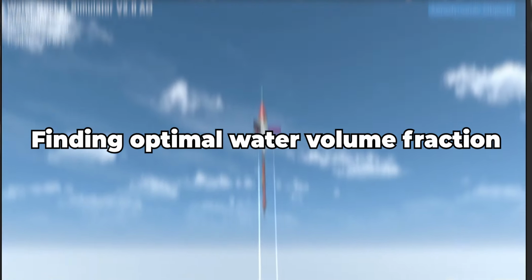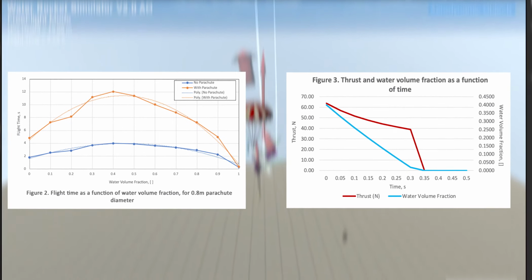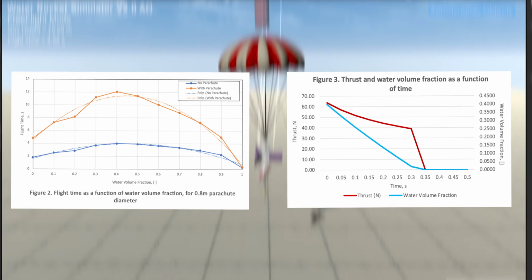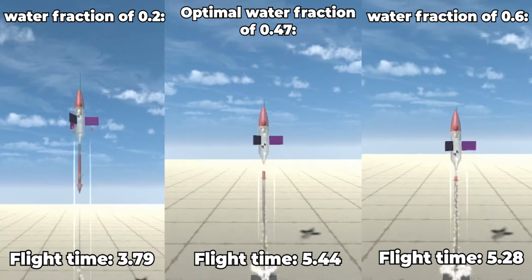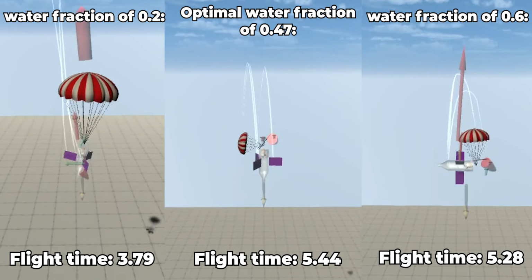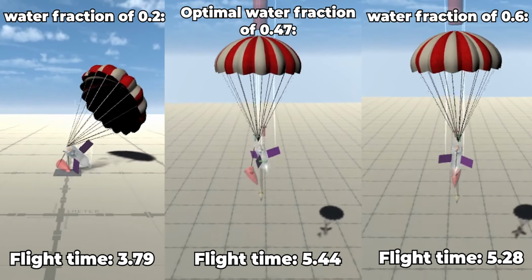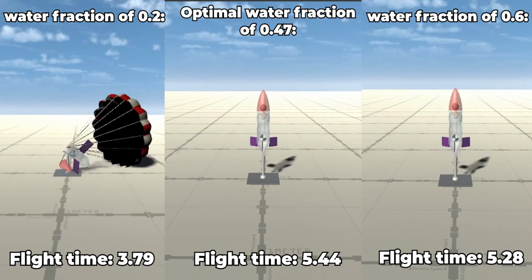Let's see how to find the optimal water volume fraction. Figure 2 shows a parabolic relationship between flight time and water volume fraction. Figure 3 shows the change in thrust and water volume fraction over time for the rocket boost phase. Water is much denser than air, so when forced out the nozzle, it generates much greater total impulse. However, an increase in water volume fraction means an increase in mass, thus weight, which acts against thrust during the boost phase. Thrust must exceed the impact of water mass on the rocket for longer flight times.